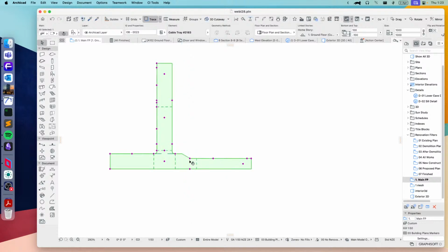And if I grab the matching one on the other side, it does pretty much what you'd expect. It reduces in the other direction. So you can grab hold of both of these and reduce down to a narrower width piece of cable tray. So that's a pair of hotspots there that do it on either side. The next one along here, we move this one, and that will allow us to split the edge. So convert this from one edge into two. I don't want to do that, so I'm just going to hit cancel at this point.